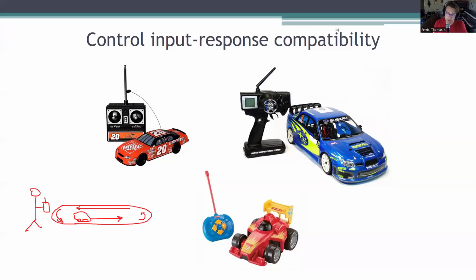And if you don't know what's going on with this one, I'll cut to the chase and tell you this is the one I think has the best mapping in terms of my control mapping, my movement mapping. Because if I got this control, I basically got to push up, right? This one's got to go up to make it go forward. But the other thing is I got to push also up to make it come closer to me when it's on the back nine, or, you know, it's coming back on the other side of that lap, right? So I've inverted that mapping when the vehicle is turned around and coming back towards me.